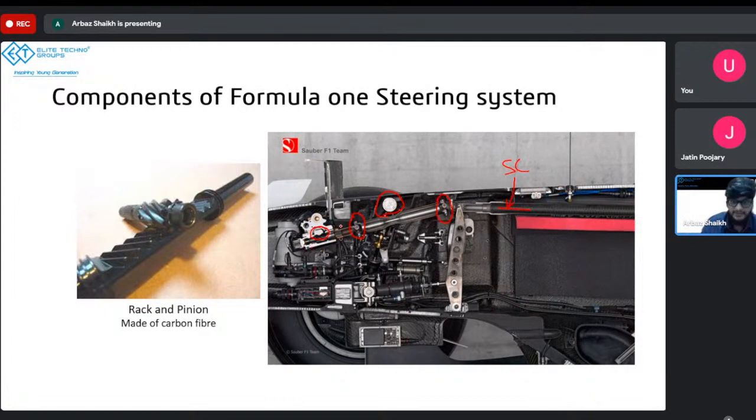If it's Ackerman geometry, it's best to use the rack and pinion with the rack at the bottom. In anti-Ackerman geometry, the rack comes on top. In this way, we can ensure whenever we turn left on the steering wheel, the road wheels will also turn left. That's one more thing that I wanted to point out.